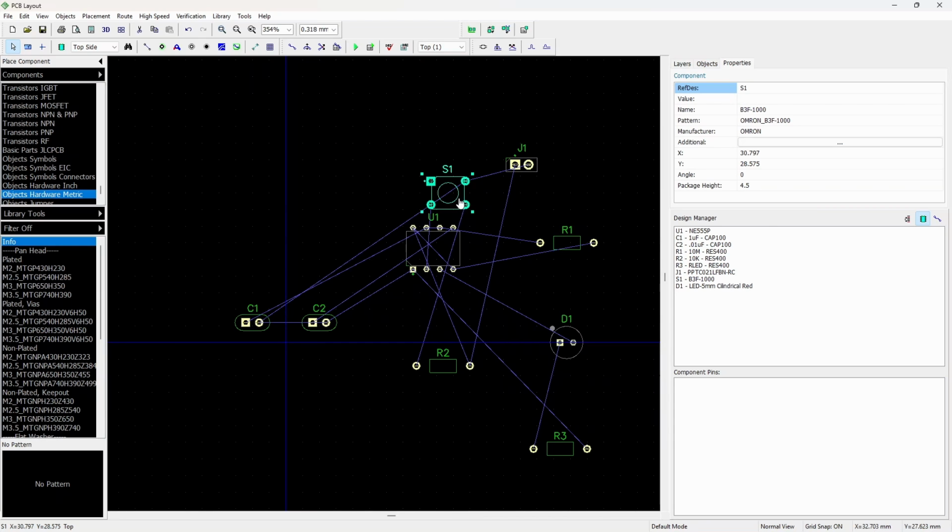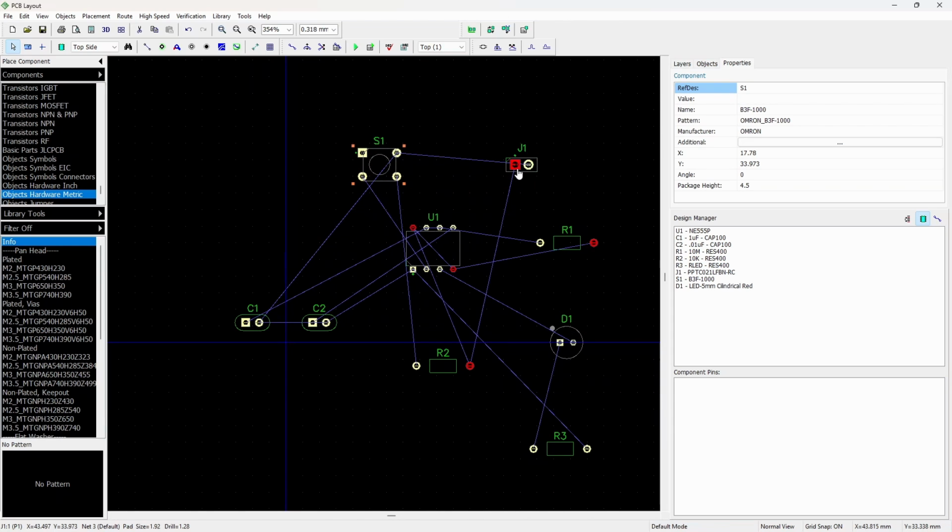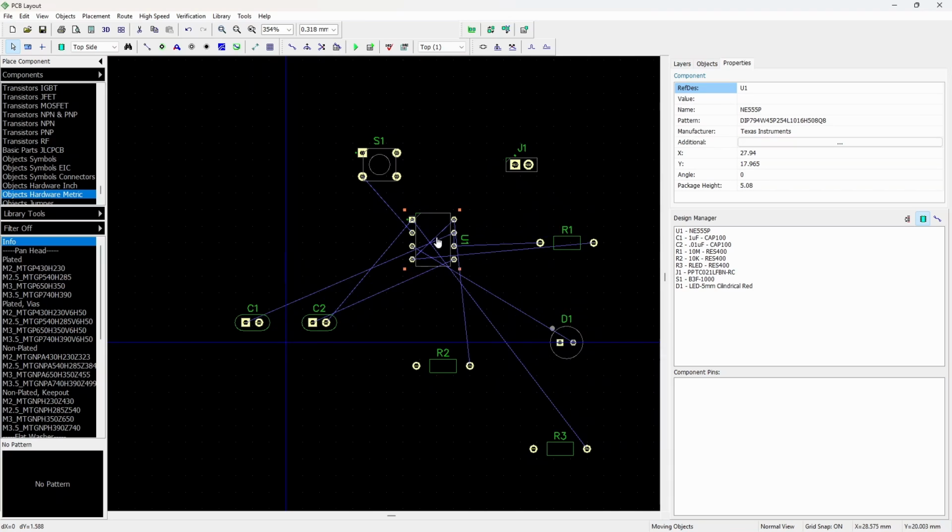If it got really complicated, we can use both sides of the board. So when you order a circuit board, it would be really rare to order a one-sided board. It would be at least two sides. And when I say at least two sides, what does that mean? There could be four-layer boards, as they're called, or 8-layer boards or more, 12-layer boards. What's actually happening is there are copper layers sandwiched inside the board. So that's much more complicated than we would do, but if it got too complicated to make all these connections, we could take advantage of the fact that we've got a front and a back of the board to make the connections we need. Like I said, this one's so simple, we probably can do it on one side.